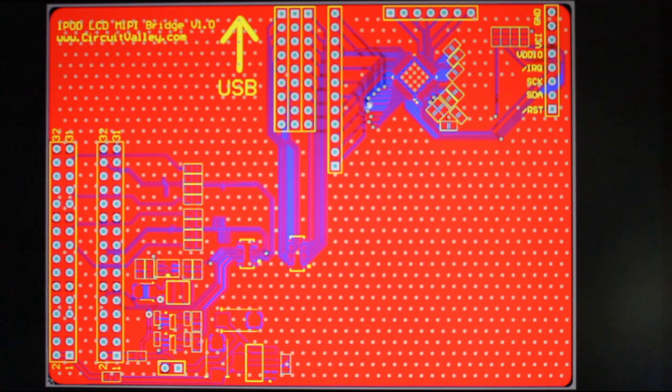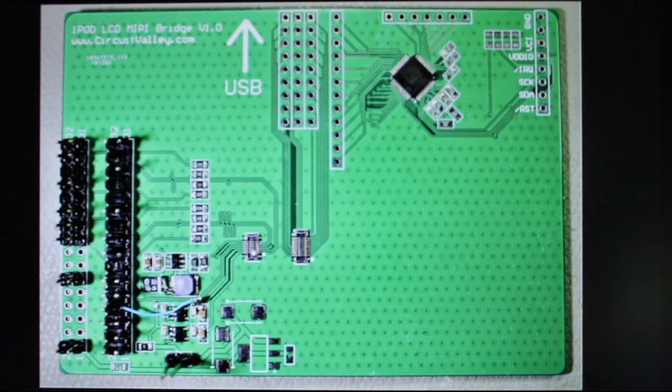Let's look at the PCB itself. This is the PCB. You can see here the connector for the LCD, and the connector for the touch controller, which is not connected right now because I don't know the correct pinout. That's why I was not able to make the final PCB. I'll do jumper interconnects here and figure out what the touch matrix connection is. These are the voltage dividers for generating MIPI signals.